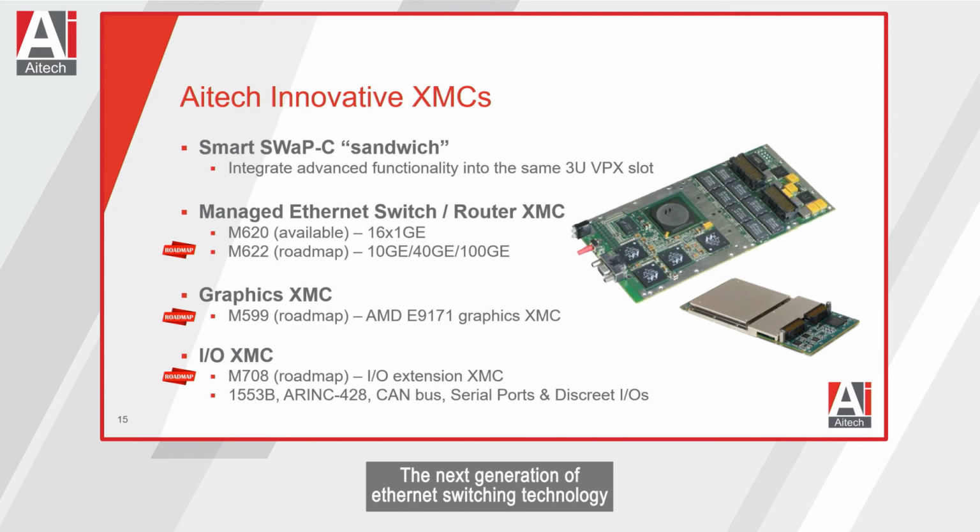The next generation of Ethernet switching technology will support 10 GigE and 40 GigE interfaces, and advancing further to 100 GigE based on 25 Gbps SerDes lanes, with fully featured Layer 2 and Layer 3 networking capabilities and very fast boot times. In addition, we are working on new graphics and I/O extension XMCs as shown on this slide.